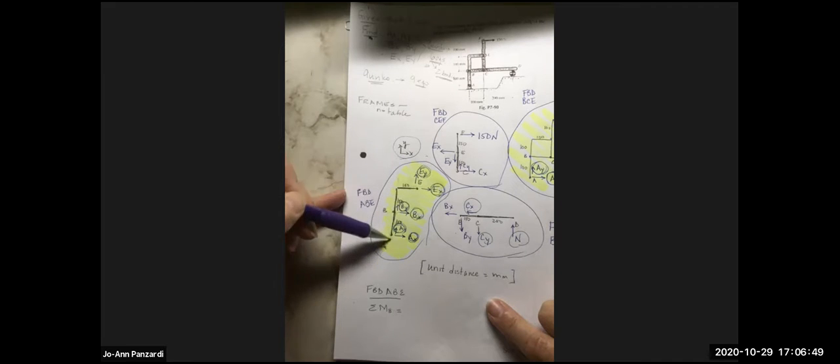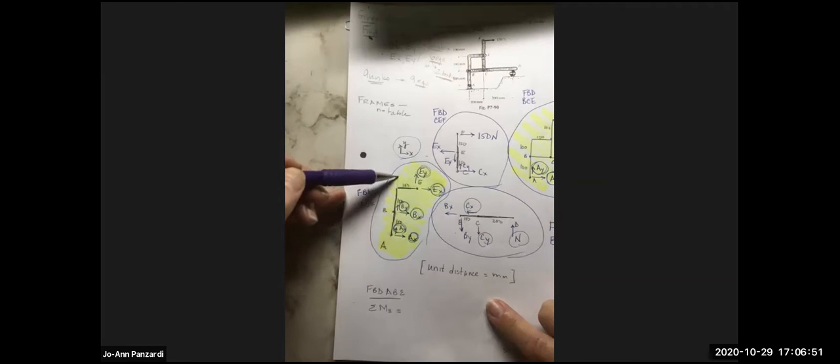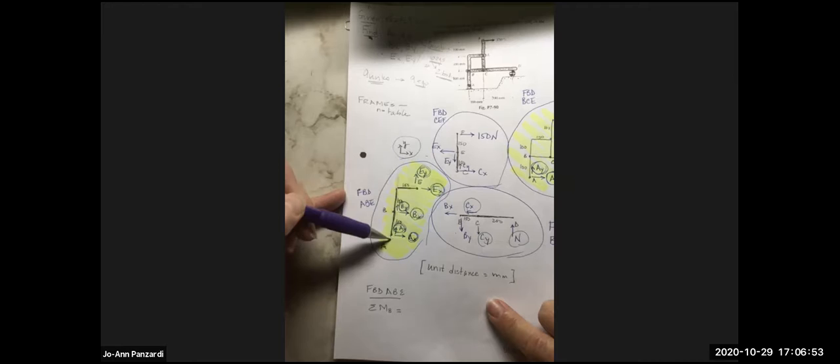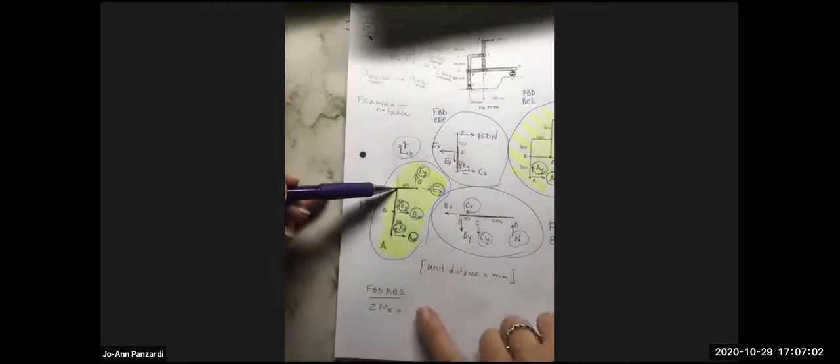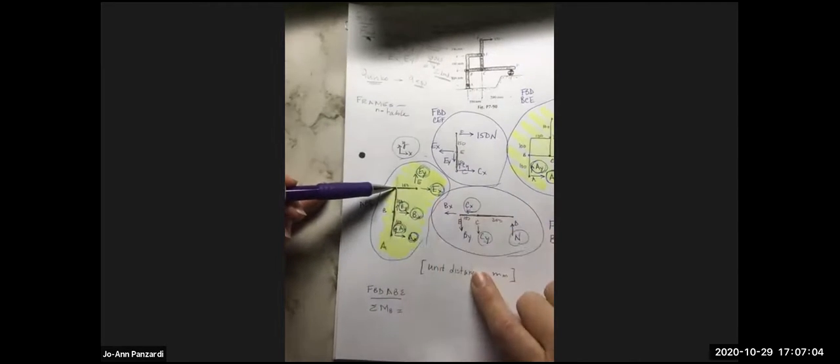Ah, okay. So if we did a moment about this line, everything would cancel out. Even EX, right? So let's try along that line, because EY is parallel to the line, EX intersects the line, and these guys all intersect. Let's try, how about this line? Awesome. Look at you, Maria.